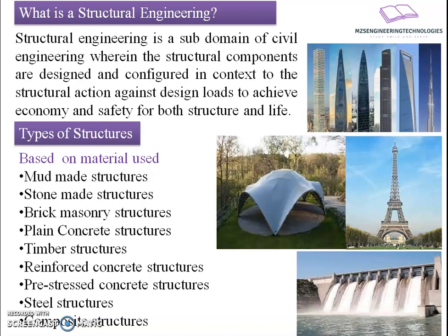With the advancement in structural engineering and knowledge about material characteristics, people have started to develop materials with higher strength and higher capability to resist forces. We are going to use high strength steel, which is prepared by using a bundle of wires replacing the single steel bar, and such a steel may have initial compression which will improve the compressive strength of the concrete. Such a section we are going to call a pre-stressed concrete section.